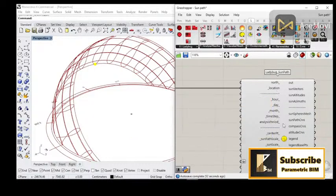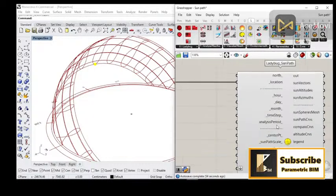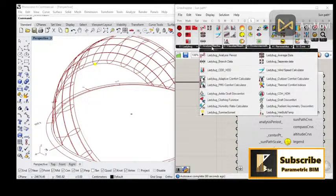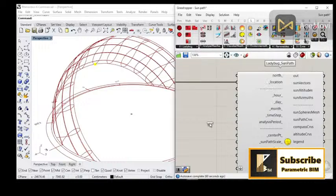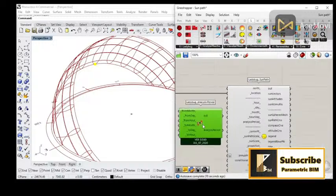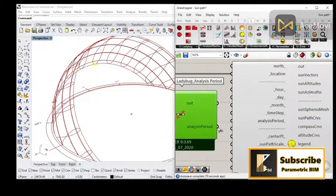Okay, so let's assign an analysis period in this tutorial. To assign an analysis period, I can go to Analyze in the Ladybug tool, and the first component is Ladybug Analysis Period. I will drag it here and then connect the analysis period in this component to the analysis period in the sunpath component.